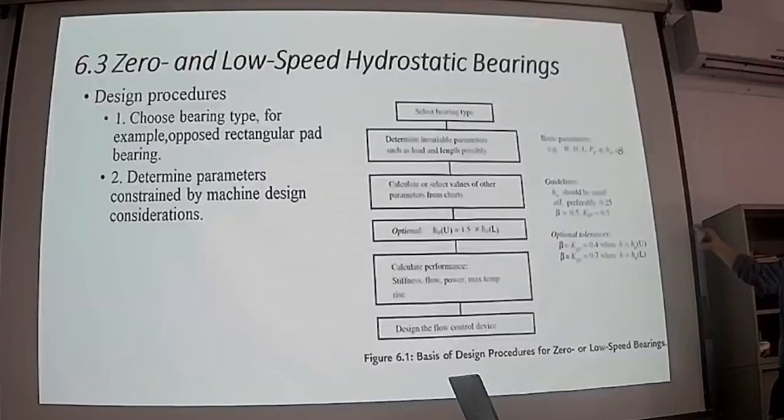Okay. The higher the speed, the smaller the viscosity grade you should select for your lubricant. Okay.